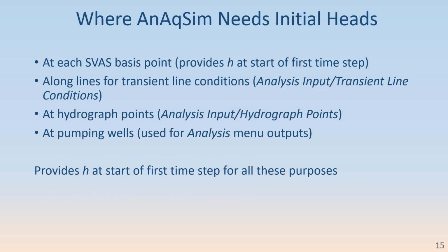This slide lists where Anaqsim is going to need initial heads. It's going to need it at every basis point, because that transient term in the equation for the first time step needs an initial head. It also needs it, or wants it, electively for some of the analysis menu inputs, transient line conditions, hydrograph points, and at pumping wells, so that you can make nice plots.